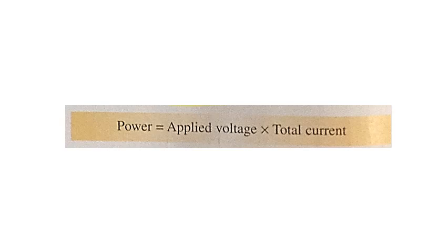For this, see figure 11-23. The total current used by this motor is the sum of the field and armature currents. The input power may be computed using Watt's law, shown on the screen. Note, however, that the output power will be somewhat different because the motor is not 100% efficient.